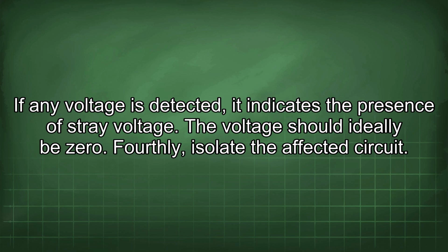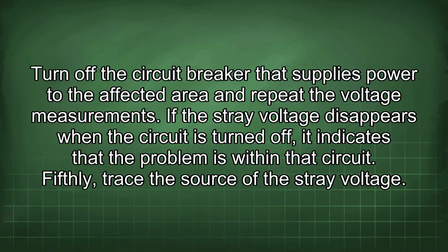Fourthly, isolate the affected circuit. Turn off the circuit breaker that supplies power to the affected area and repeat the voltage measurements. If the stray voltage disappears when the circuit is turned off, it indicates that the problem is within that circuit.